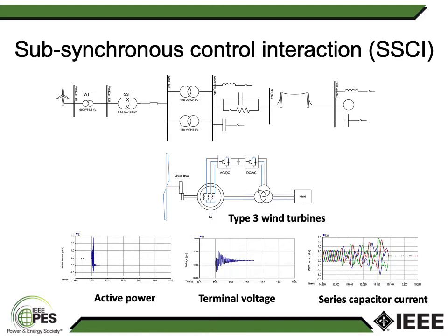Essentially, what would happen is that under radial or near radial connections, as soon as you switch in the capacitor, there would be some volatile dynamic responses associated with both the wind turbine and the series compensated line. In this particular instance, which is based on a published IEEE paper that I had personally around 10 years ago, the wind turbine essentially protects itself by disconnecting from the grid. And it's needless to say that the reason we call them subsynchronous interactions is because the dominant frequency of oscillations is below the network fundamental frequency. What I'm going to discuss from the next slide is what we had observed in Australia and how similar or dissimilar it is with respect to this known form of SSCI.